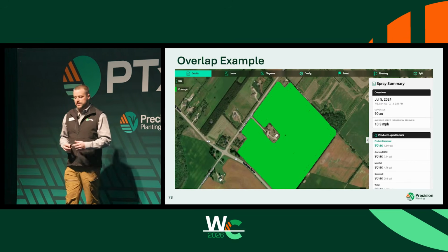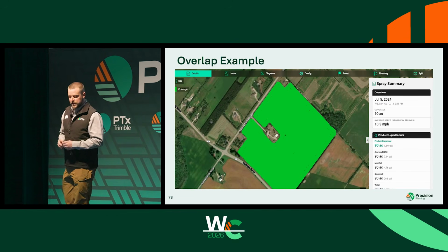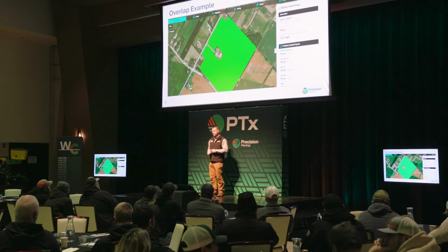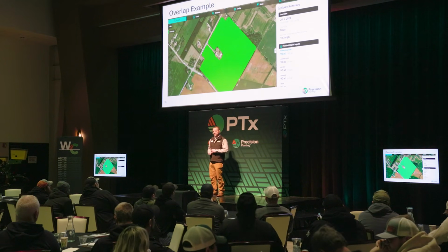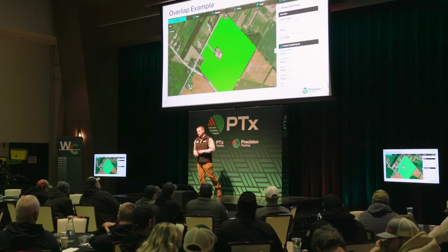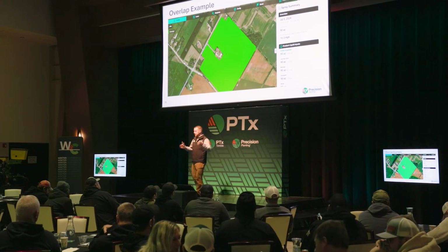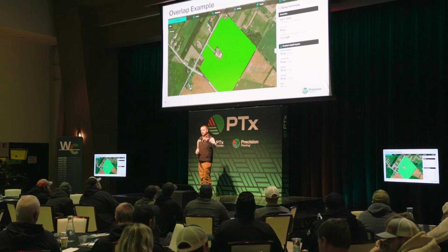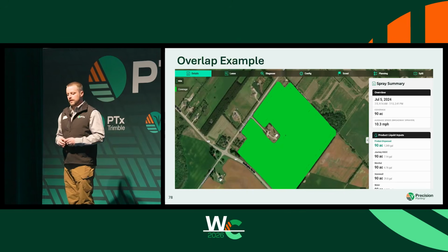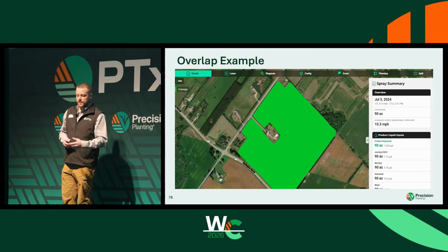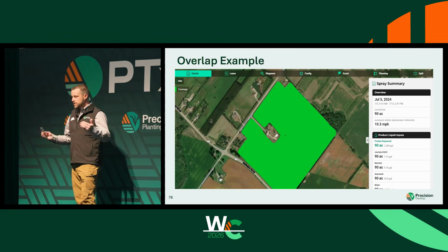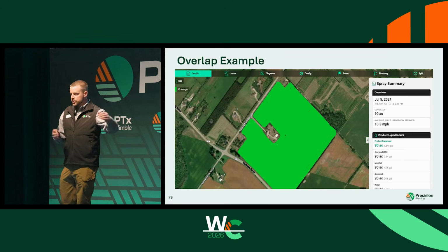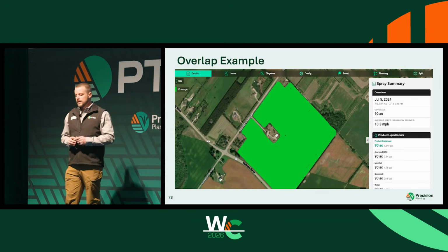Okay, so just kind of as an example, as we're still trying to quantify some of the numbers, as you think about your operation today, when you go to buy seed and fertilizer to put out with your air seeder, with your granular system, if you don't have any type of a swath system, from my conversations with most of you, I'd say you would look at probably a 10% overage of what you plan on for acres. Okay, so if I look at this example of this system, this is a drill that just has granular rate control, so no metering system on it, like what you see here right of stage. We're just controlling the entire meter itself.